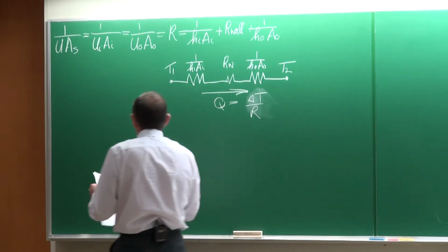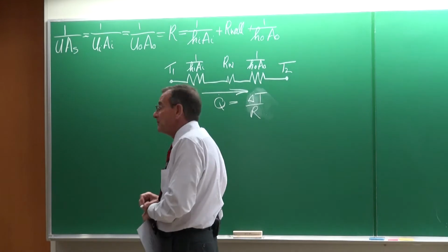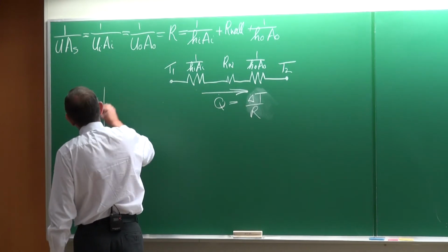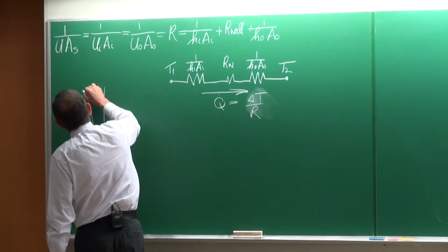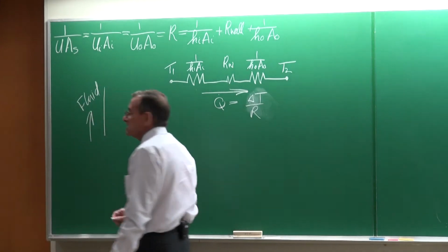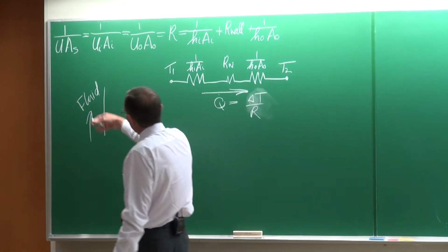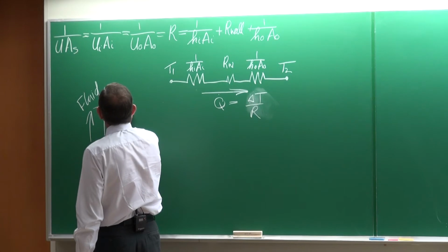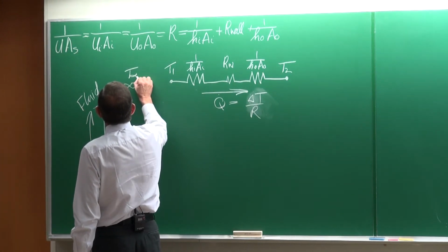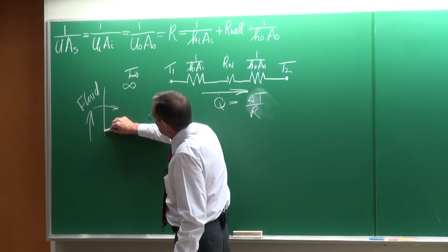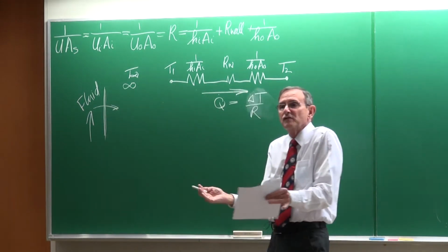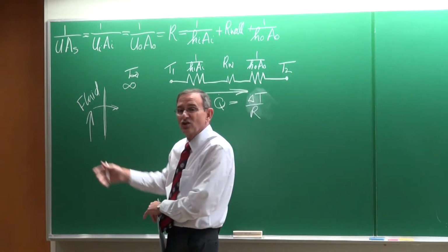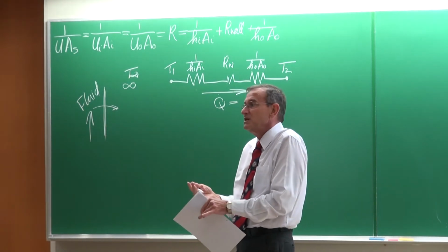Then we've looked at this total surface area. In many cases, if you've got a heat transfer stream, let's suppose you've got a fluid here on the inside, and it can be a single phase fluid, or it can be a fluid that is boiling or condensing, and you would like to transfer heat to the environment. Then you can make use of this surface. So that will be the surface of heat transfer. Normally, you will see that the air requires a lot of surface. You're going to use many square meters.